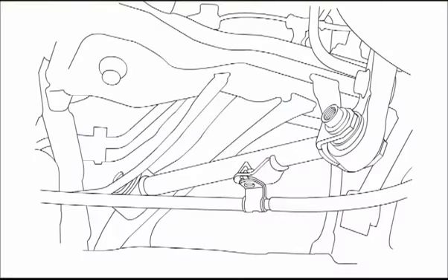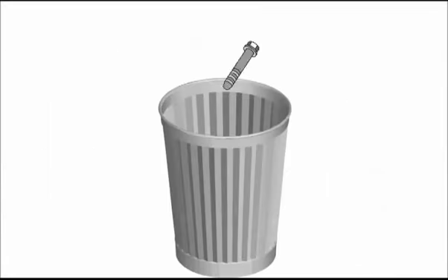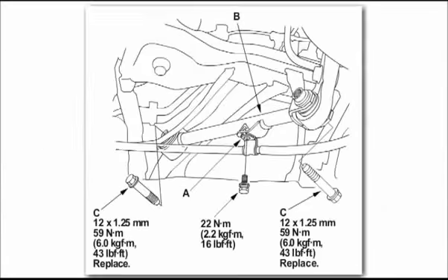Due to their design, some fasteners can only be used once. Consult the service information to verify if a fastener can be reused or needs to be replaced with a new one. Reusing a one-time use fastener may cause it to work loose.